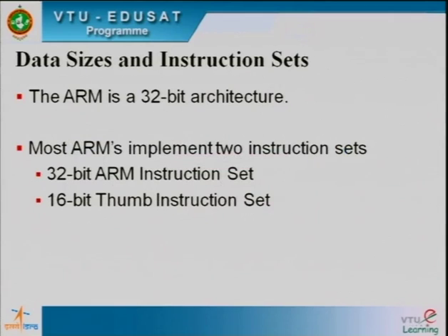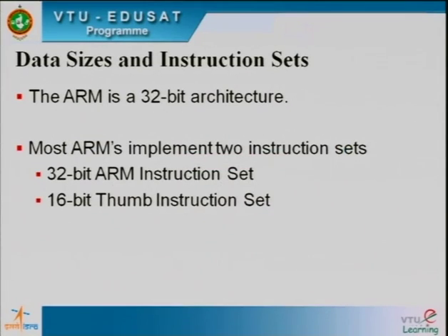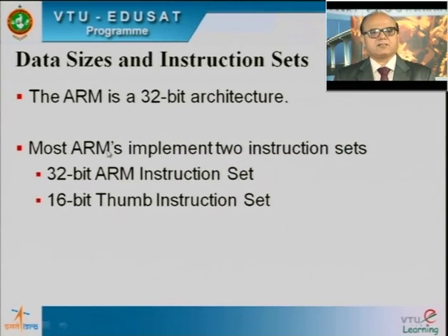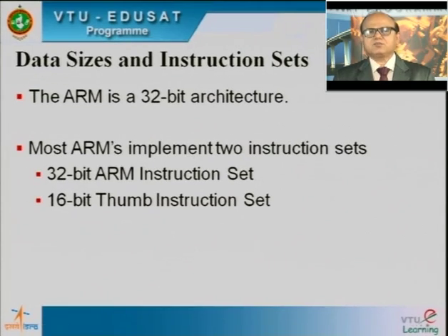Now the data size and the instruction sets of the ARM. ARM is a 32-bit architecture, and most of the ARM family supports 2 instruction sets: a 32-bit ARM instruction set and a 16-bit Thumb instruction set. These are the 2 instruction sets that any ARM family processor supports.